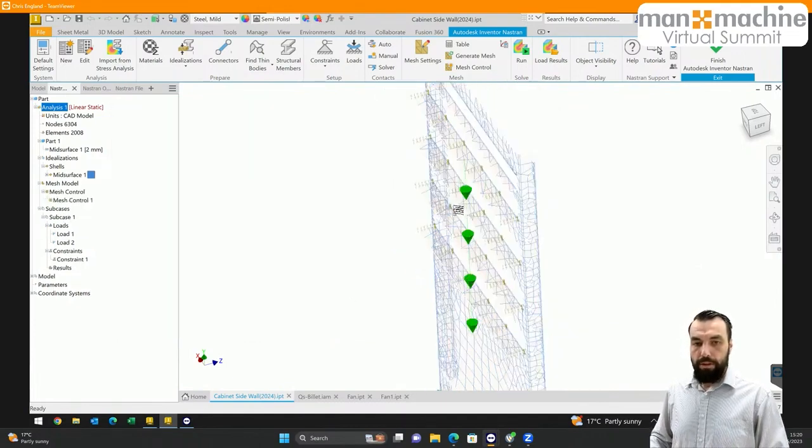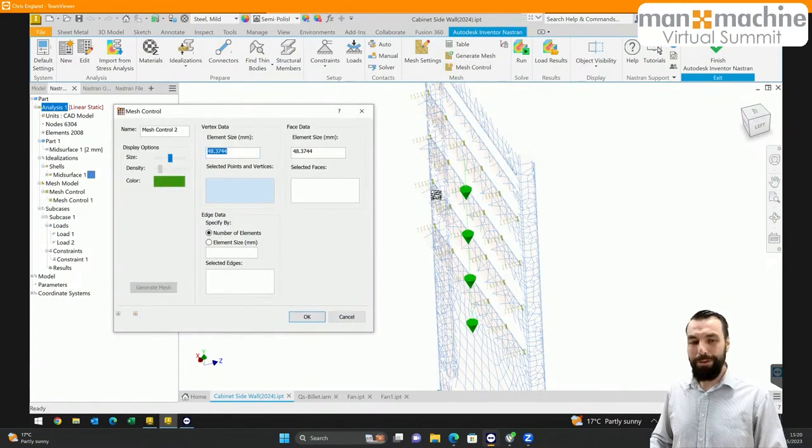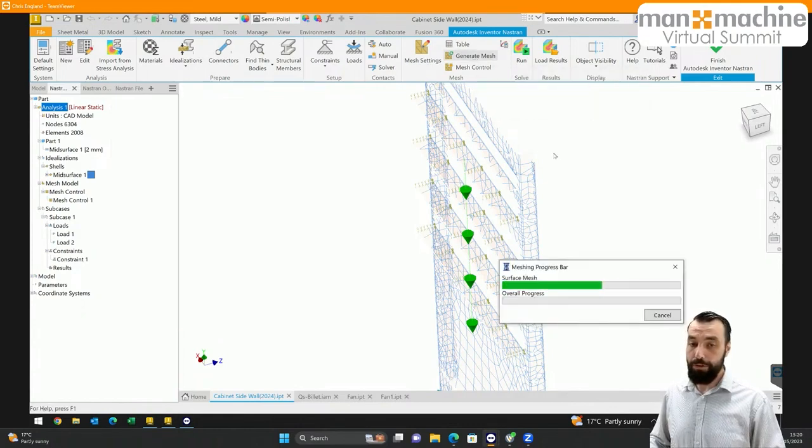and I go OK. So I just missed one of my features. Within the local mesh control, we now have the ability to generate the mesh, but I can't select it now as I've already hit the OK, and I've ruined my whole punchline here. But anyway, there is now a generate mesh button within the local control, so you don't have to hit OK and generate outside. I guess the old habit's embedded in me, and I just went for it.